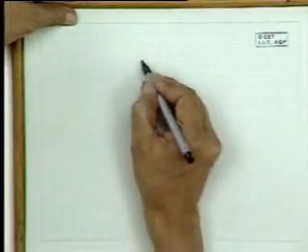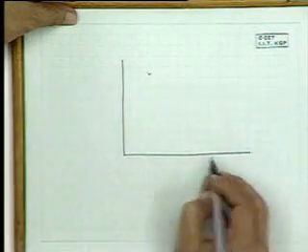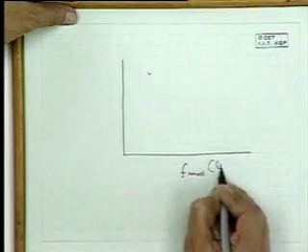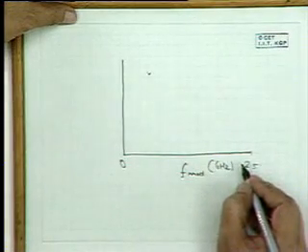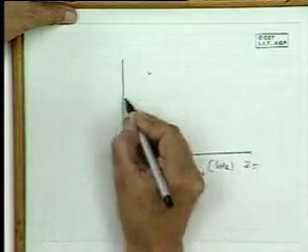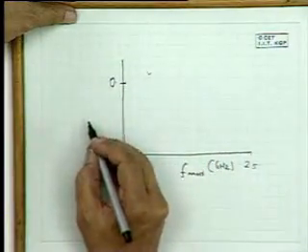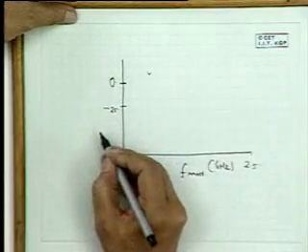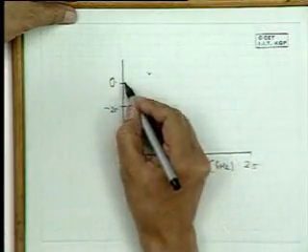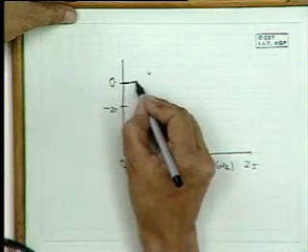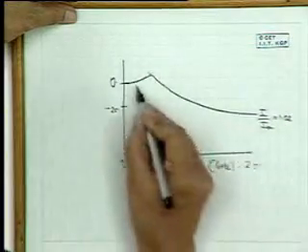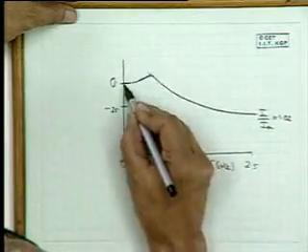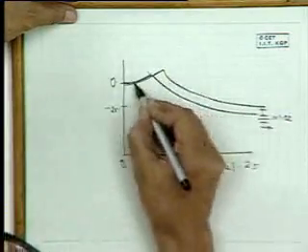And for example, what is the modulation frequency that you get? In gigahertz, going from say 0 to say 2.5, as a function, this is in dB, the output in dB. Now, if you have I by I_th rather small, just a little more than threshold, then the frequency response falls. But if you keep on increasing this,